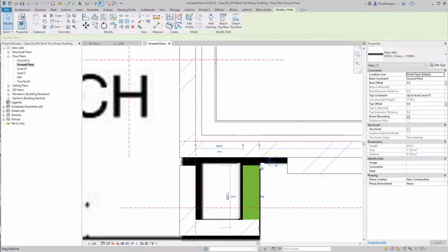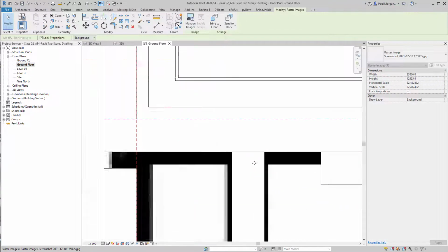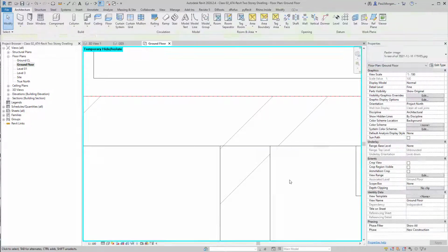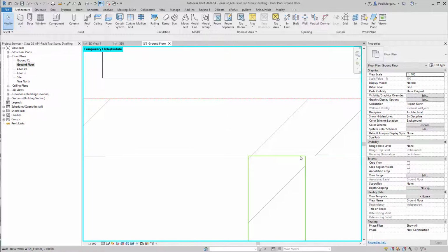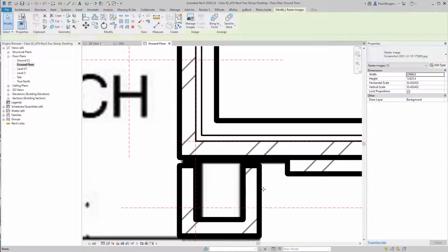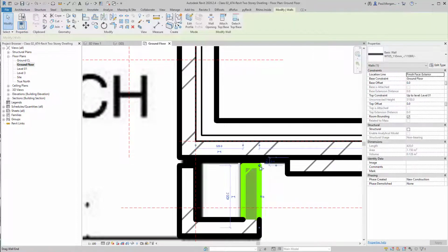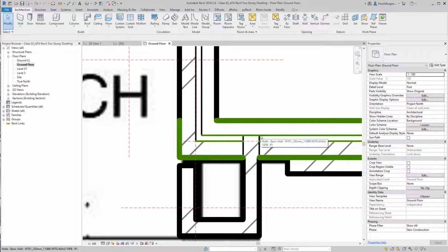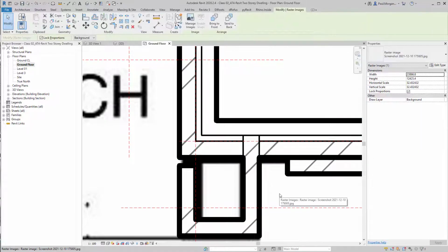What that means is when I drag that wall up to here, you'll have this line which defines that. In fact, I'll just hide the image behind. So you have this line here that defines that one wall ends and the other one begins. If I don't disallow the join, what will happen? If I just drag that in there, you can see it meshes the wall together, and we'll drag this wall and meet it with the structural element of the next wall, which is, of course, the timber structure. So you end up with this weird looking graphical situation, which is not right.